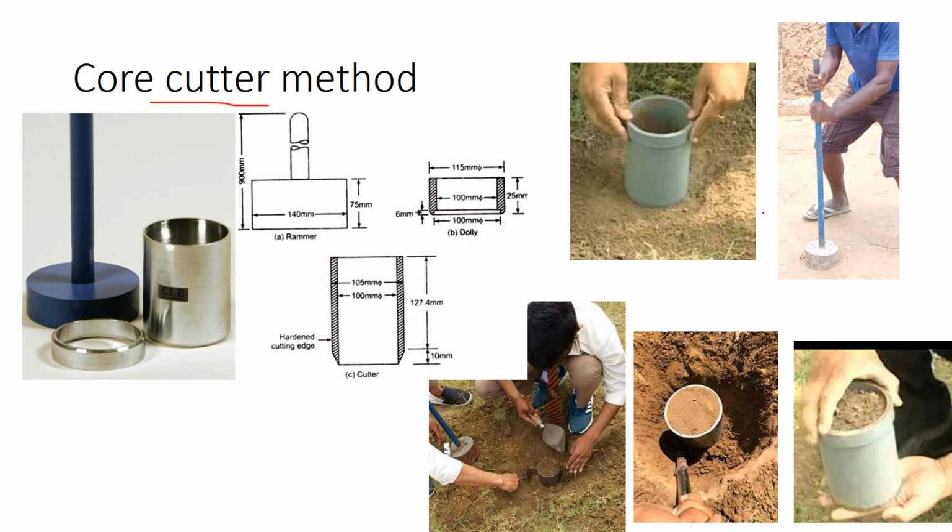Then we have to remove the surrounding soil carefully, and then remove the dolly and cutter together. Finally you will have soil inside your cutter.